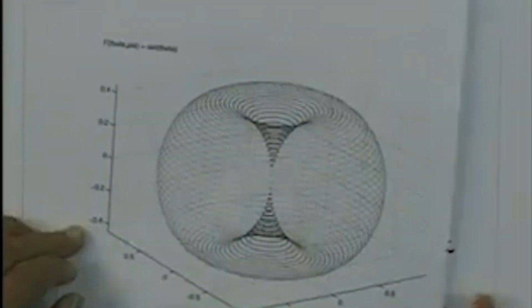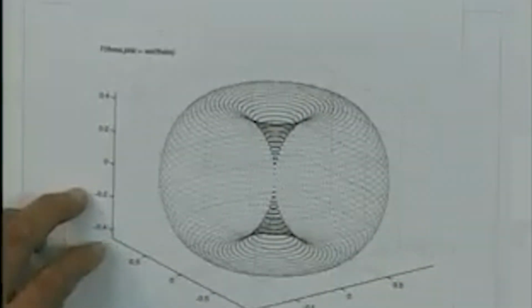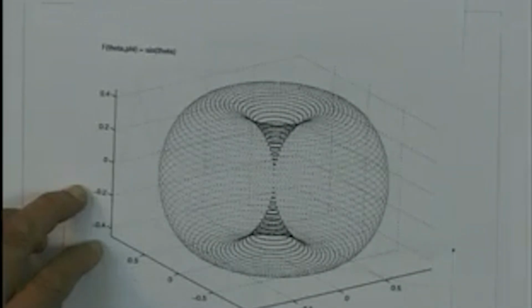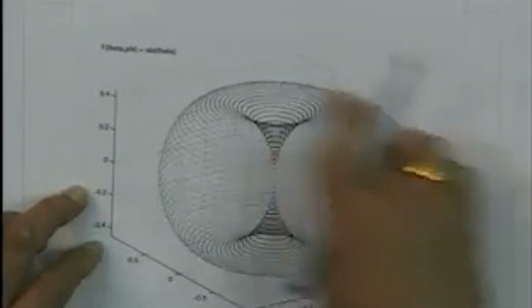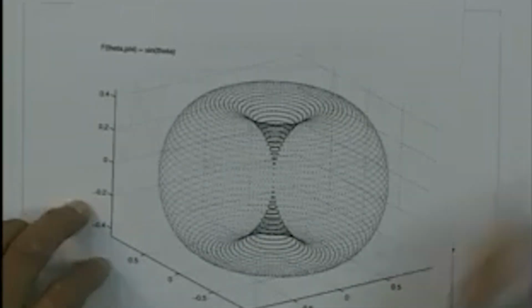As we argued, it is not possible to get an isotropic antenna in practice. So, you might get an isotropic nature maybe in a plane, and that is what your Hertz dipole does. So, this radiation pattern is not uniform in all directions, but if I go in a direction in the H plane, my radiation pattern is a circle.